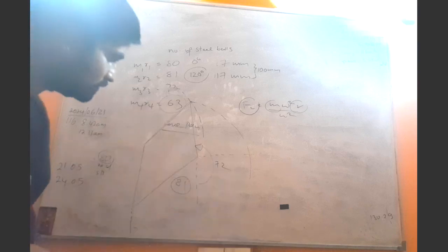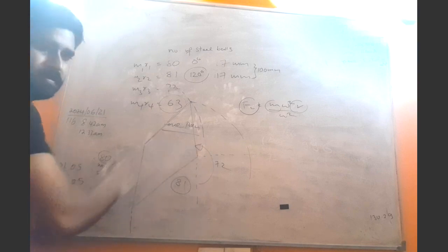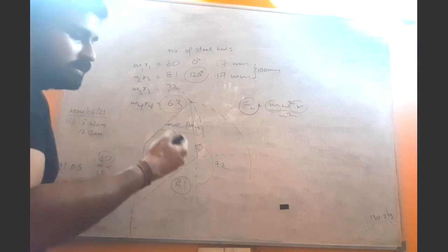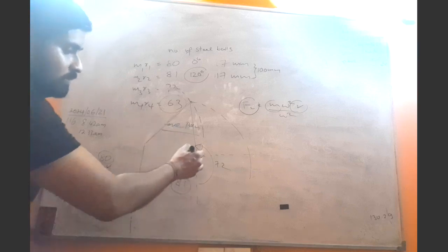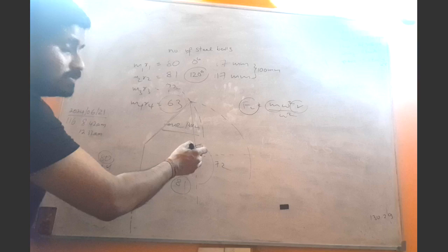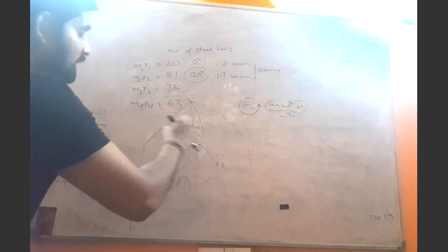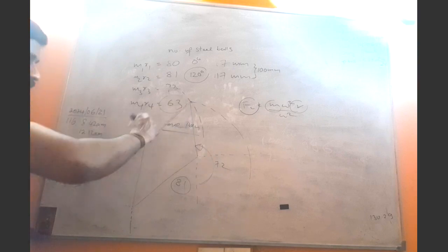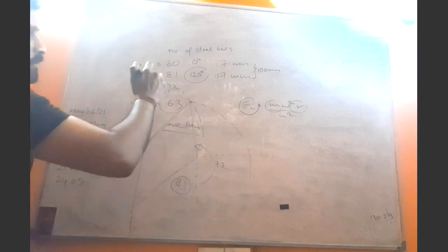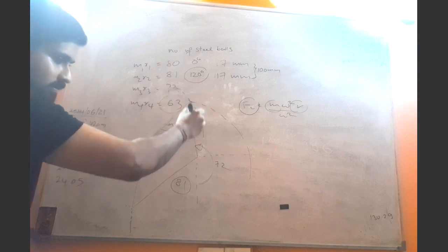When it comes to the third vector, the previous vector is the second vector, and the position where the second vector finishes is over here. So start measuring the angular position of the third vector from where you stopped in the previous vector. So you can measure this angle. When it comes to the fourth mass, this vector represents its centrifugal force. What is the vector drawn before that? This one.